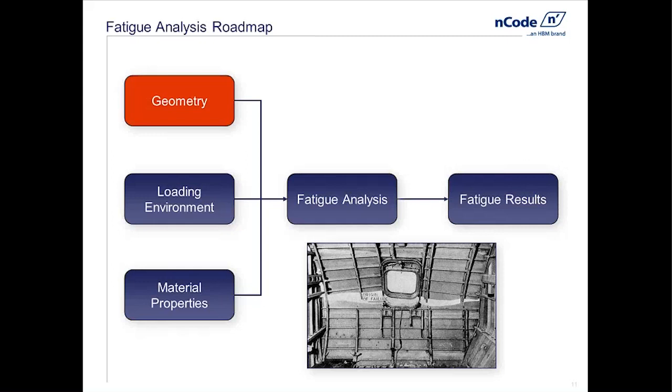This is an example right here of one of the first commercial jetliners. This is called the de Havilland Comet. This is looking out the window, so this is inside the aircraft. This is frightening in one respect because this is a crack that's probably about 1 meter long, maybe even 2 meters long. This is miraculous at the same time too because it did not cause immediate failure.